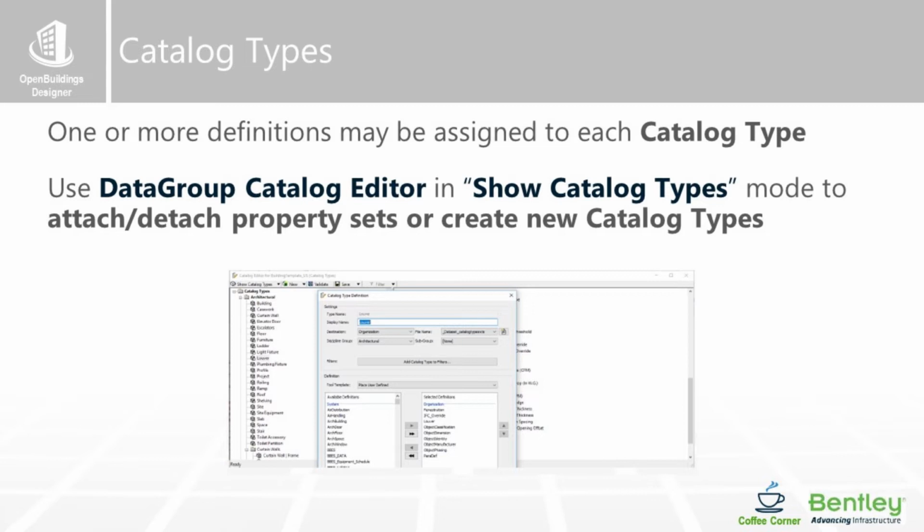Don't do that. Set yourselves a champion. Appoint somebody within your project as the administrator of your data group system to make sure that everything is properly set up as early as possible. Look at your BIM execution plans, understand the information requirements that you need to deliver, create those property definitions, create those catalog types, and control it in a deliberate manner.